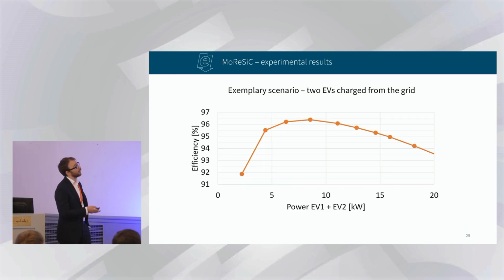And the efficiency we got for this two-stage conversion is 96.5% peak. And I would like to make a remark here. Of course, this is a scaled system. So one would say, why such high voltage here? But this is a scaled system again. If you do 10 times higher power, then the efficiency would be, of course, really nice. So this is something to take notice of.